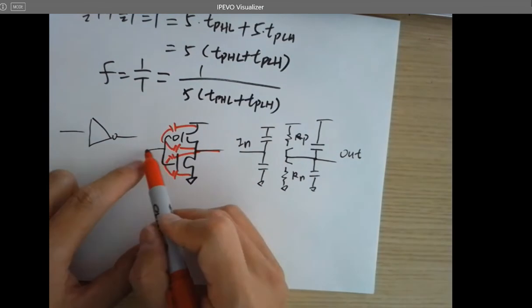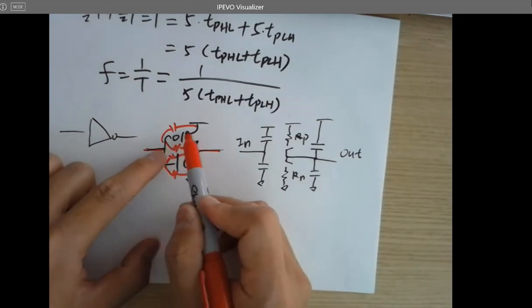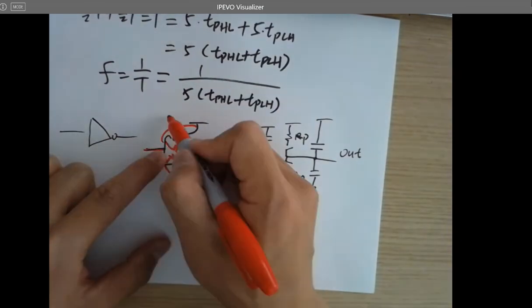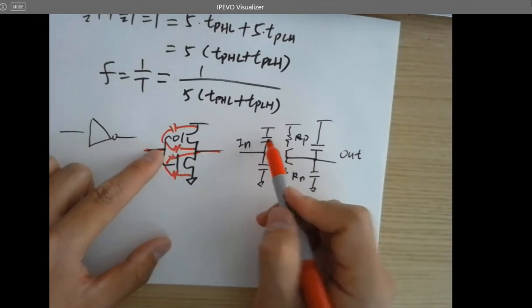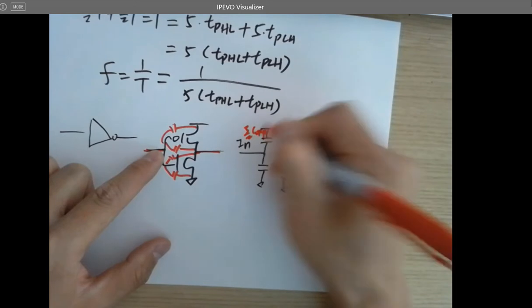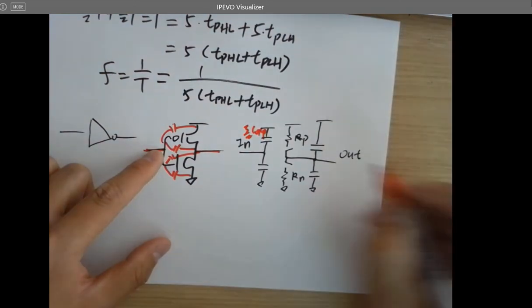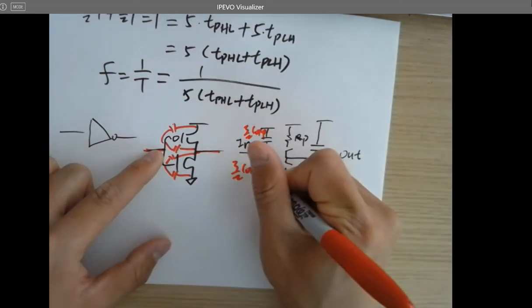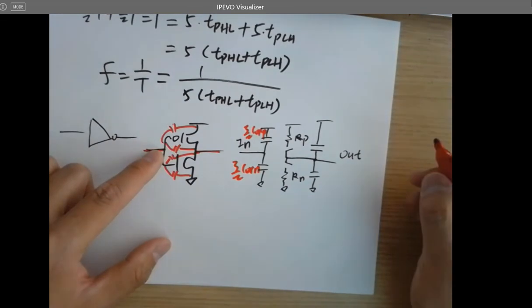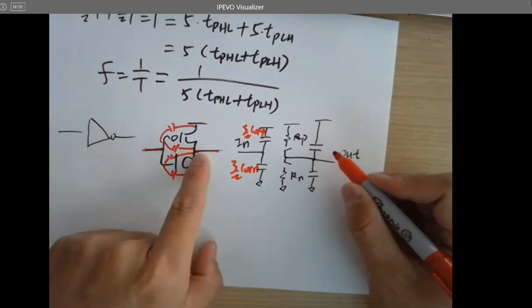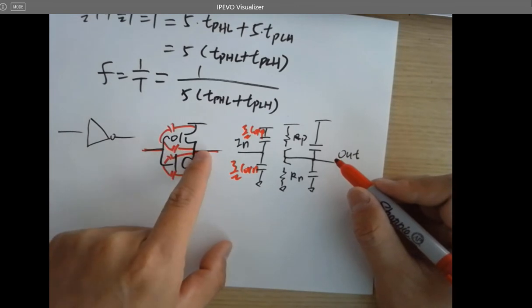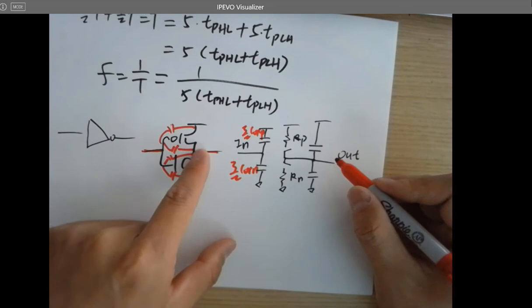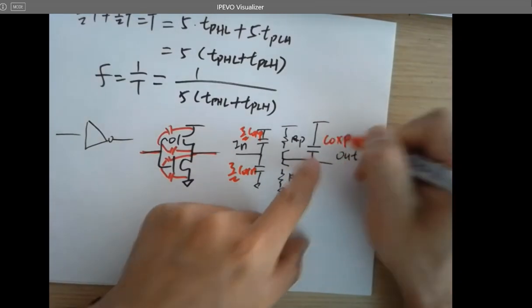So for the input, when you are looking at the PMOS, you've got a half Cox here and 1 Cox here. So what's the total input for the P? 2/3. And same here, Cox N. What about this one? It only has the Miller capacitor for this cap as the output in terms of the PMOS, so this one will be Cox P and this will be Cox N.